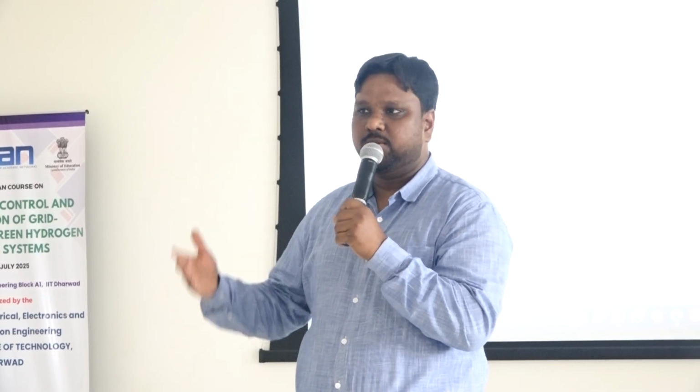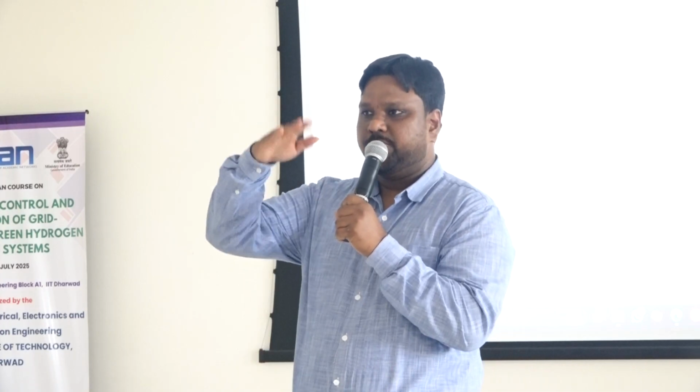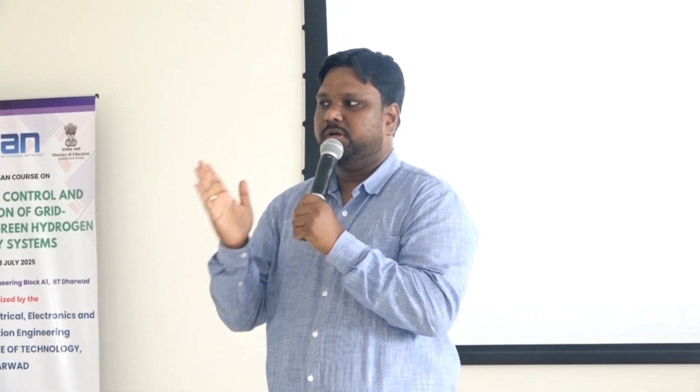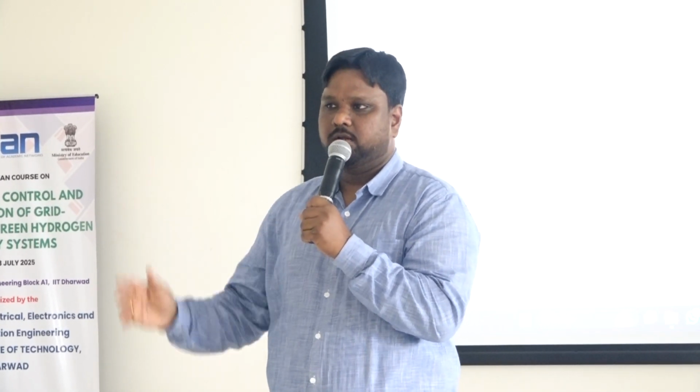That carrier is very fast, a high frequency carrier, which can be 10 kilohertz or 20 kilohertz. Through the comparison the output becomes high and low, like a pulse generator. That is done through the SPWM scheme, but at the end you generate the pulses. The pulse frequency becomes 10 kilohertz, right?